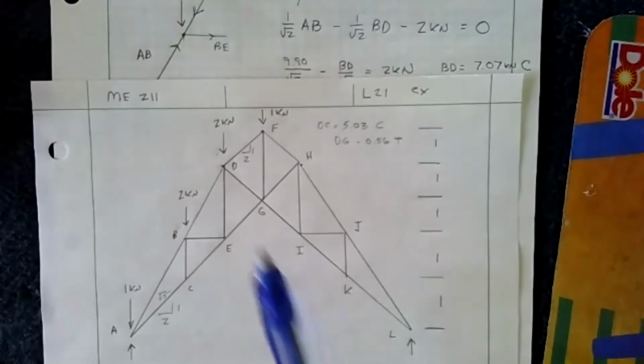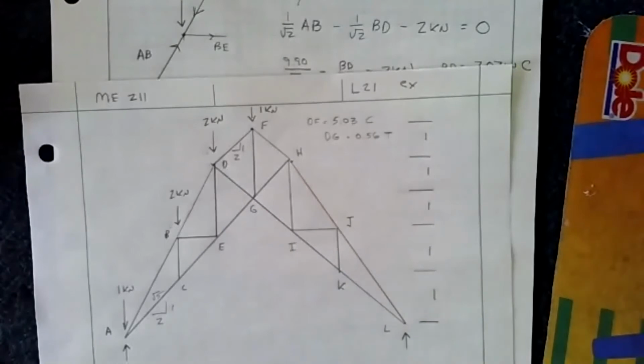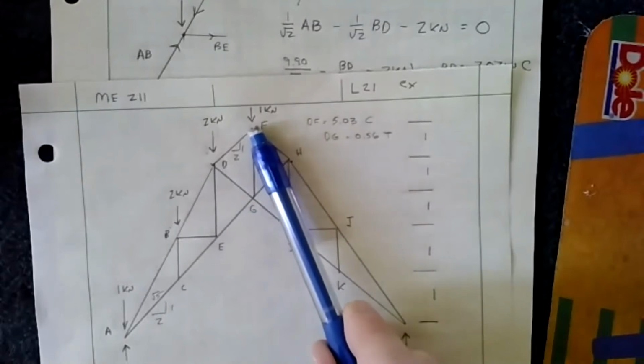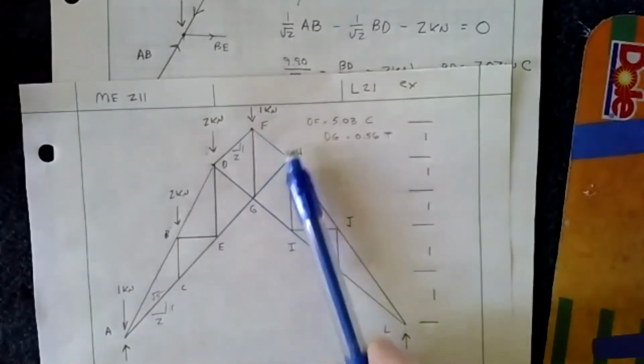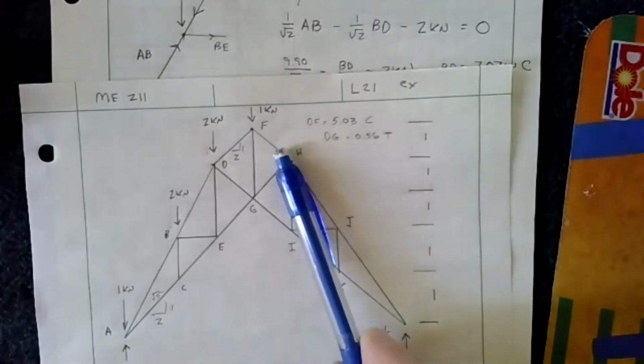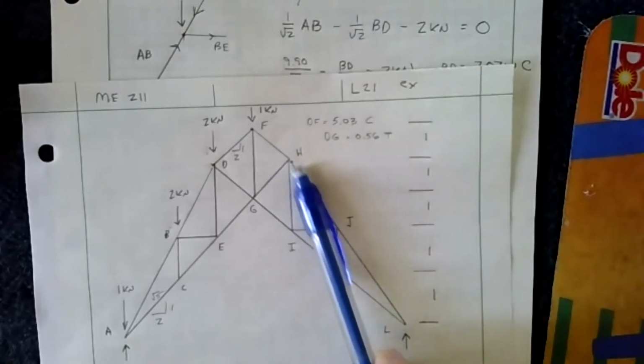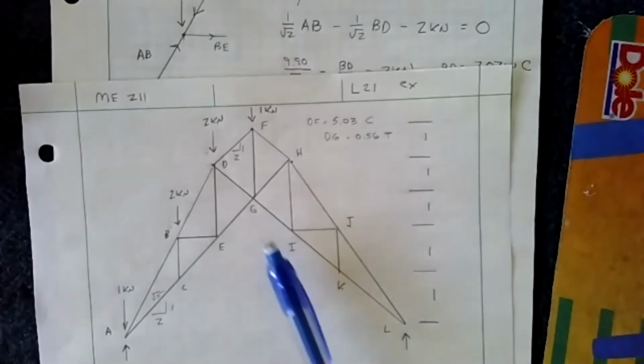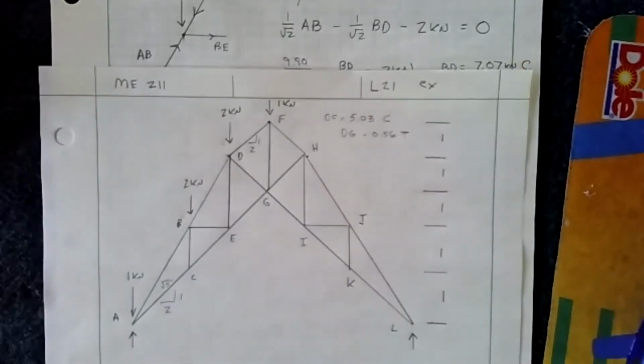And again, you could work your way all the way over. That's not necessary at this point, but if you'd like. Once you have those two, you can solve for FG, FH, and then GH. And once you have this, then you can go down to H, solve HJ out through JI. Once you have G, you can get GI, which is going to be equal to IK and KL, and you'll have the whole truss. Now, that's a lot of work to do. That's why on the homework, I only give you a few of these because they are time consuming. But once you do a few, you should have no problem. So hopefully that made sense.